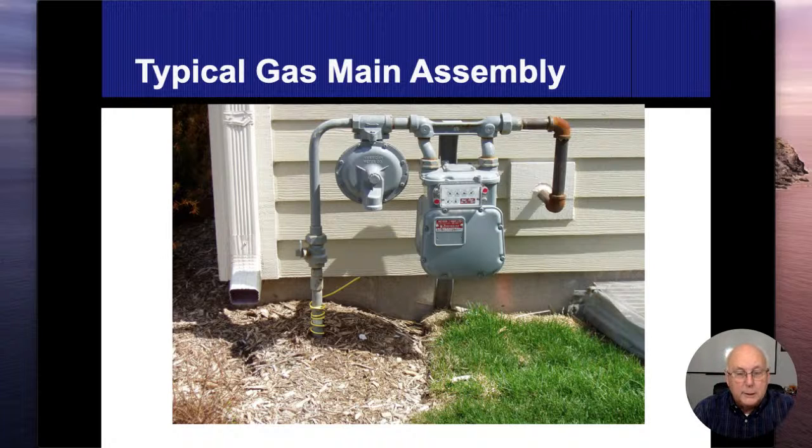One of the questions I like to ask people when they start in this business is, should we ground our electrical system to the gas pipes? And a lot of people look at me like, what, are you crazy? No, because if there's a spark, it's going to explode. That's not the right answer, all right? If we have 100% natural gas, it's not going to explode, even if I start getting sparks to it. If I have a leak, that's a problem, and any spark nearby that leak can create it, but grounding isn't going to do that. The main reason why we don't ground at the gas pipe is because it's plastic. I don't get a good connection to the earth.